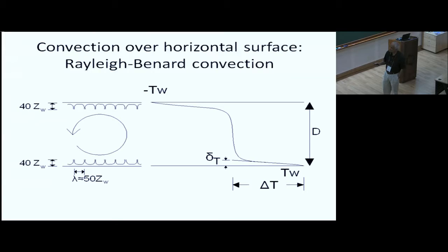The classic example is Rayleigh-Bénard convection, where you have a temperature difference between the lower plate and the top plate. When the convection is turbulent, typically you have several structures, which I will show later. Roughly, you have some sort of dynamics or plumes close to both walls, and then you have an outer flow. You can define a conduction layer thickness based on the gradient of temperature at the wall. Because of convection, you typically have a core where the temperature is almost constant. It's isothermal.